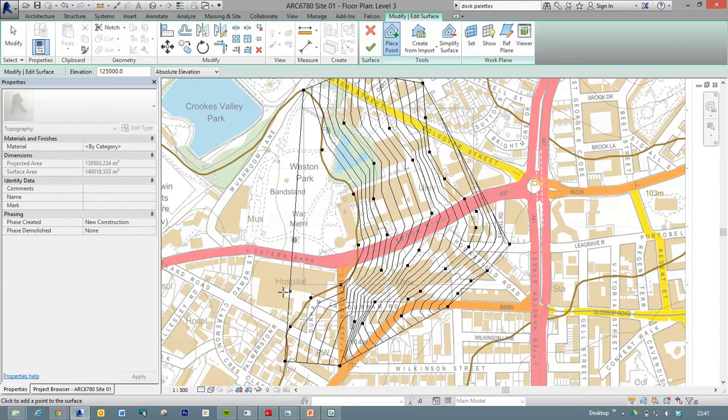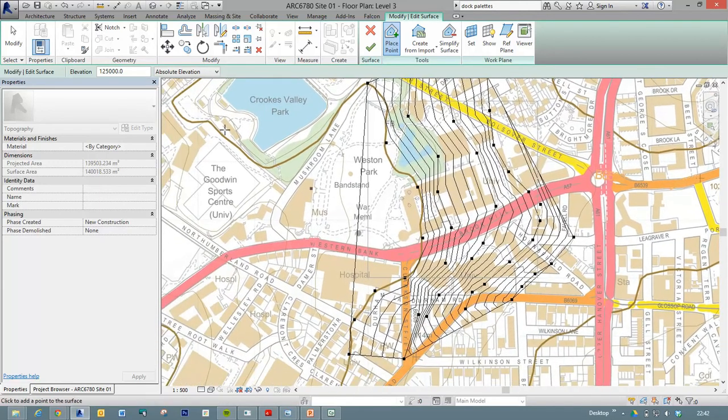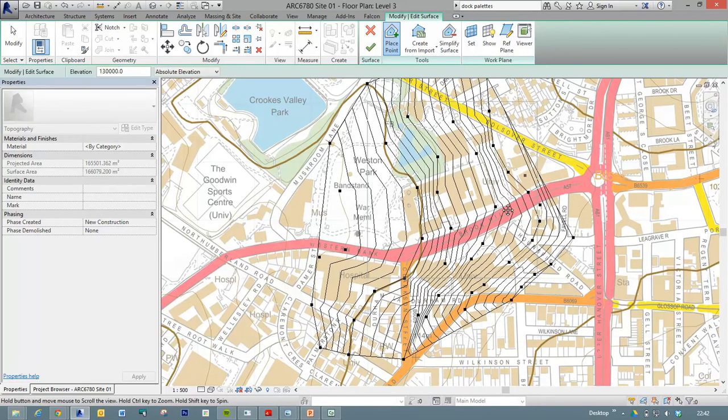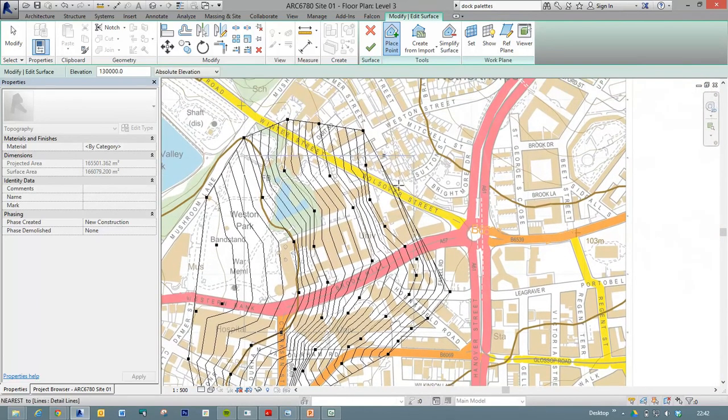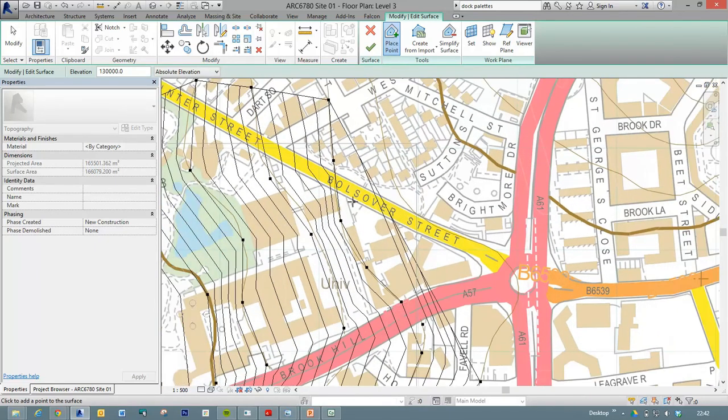We're getting there. We'll go to the next contour up, because although it's off the edges of our model, you do need to input that information, or as you can see, it's just leaving the top level flat. I'm just clicking along that next contour there. Okay, that's all looking pretty good, except at the bottom end we're rather lacking some information.